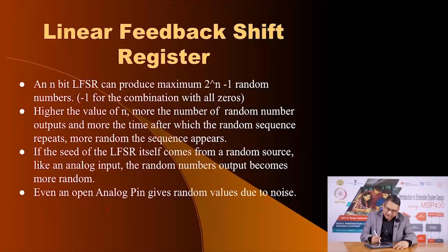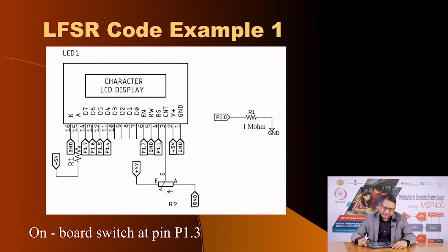If you have a microcontroller such as MSP430 and it has analog input, if you put a large enough resistor, or even if you keep the analog input open and if you sample this signal, you will find that it reads a random number, or a value which you cannot predict, and this could act as a seed. So, what we have done is we have used this mechanism to illustrate a couple of code examples.